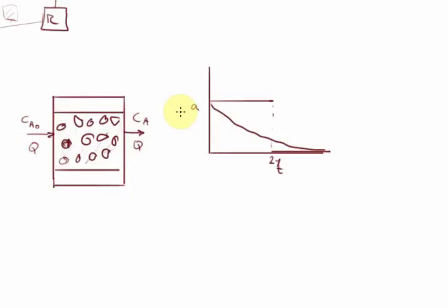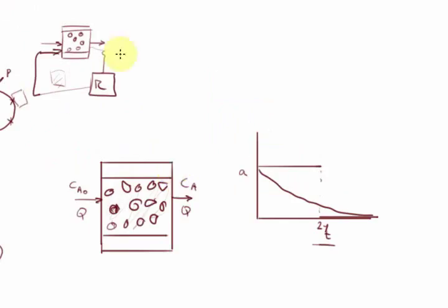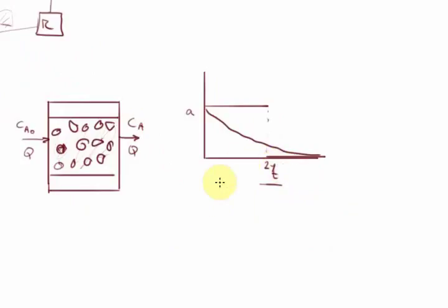And so we are trying to identify what variables we can use to accommodate this loss of activity over 2 years. We accept that after 2 years, we have to do something more drastic. So after 2 years, yes, we do have to look at the shutdown and replacing this catalyst and perhaps regenerating it offline or something. Without having constant regeneration, if every 2 years we have to regenerate, that's acceptable. So we have that possibility.